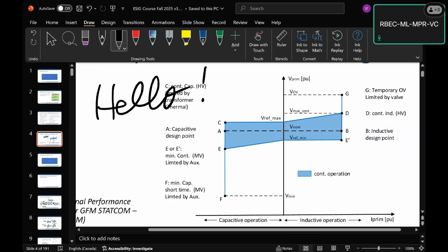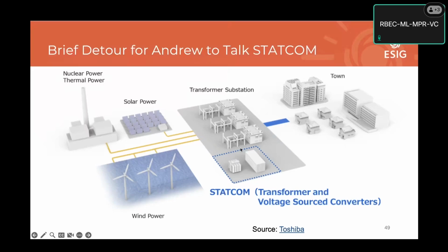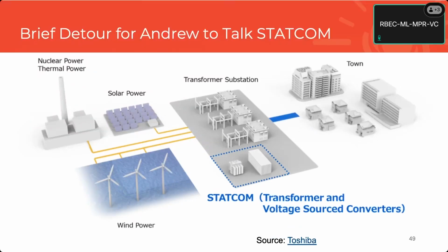Yeah, and just while I plug in here, because they're expensive and because they could be the result of your interconnection study, it underscores the importance of actually using the right models and studying your plant the right way, because it's often much, much cheaper to tune something or use a different model than it is to buy a STATCOM, just in general. And I've done that firsthand a few times in my career so far. So let's see.